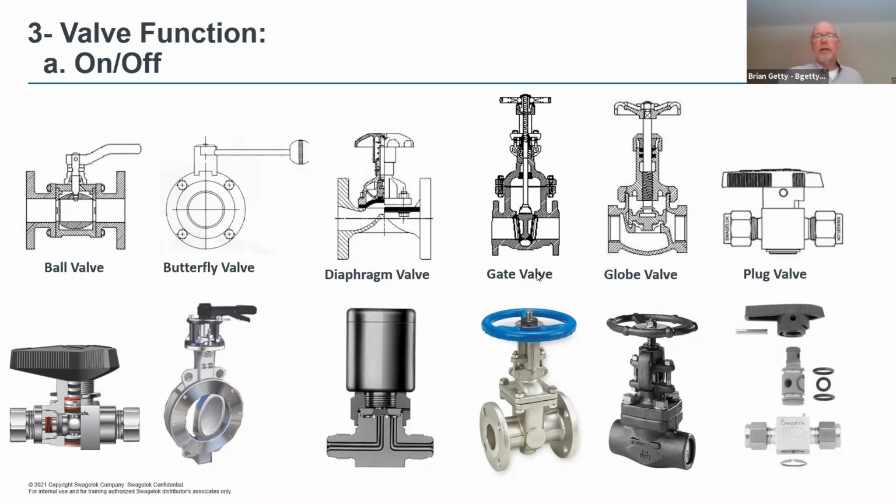Okay, the gate valves. We've all seen a lot of different gate valves. A gate valve is very similar to a ball valve. You've got very little restriction to flow through here. It's almost full flow. The only thing is in high pressure. It can also be used as a regulating valve, but in high pressure you can get a lot of cavitation and early wear of the valve as it is opening and closing, or if it's being used in a throttling situation.